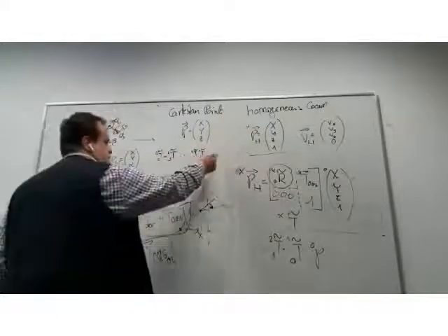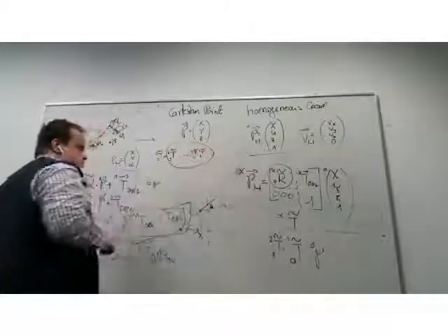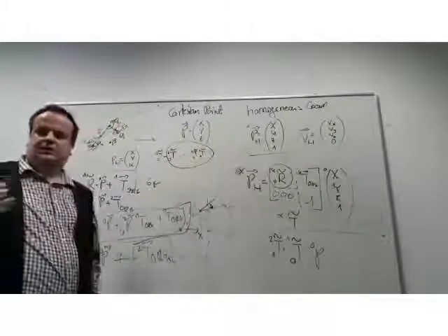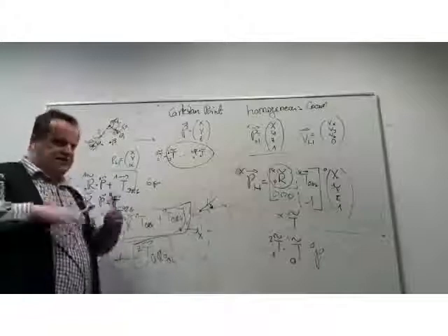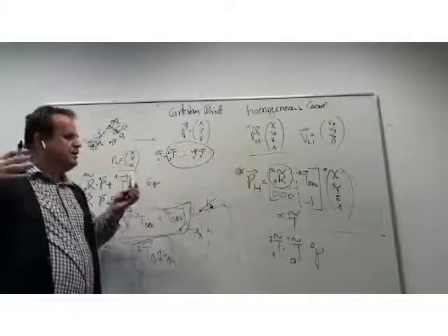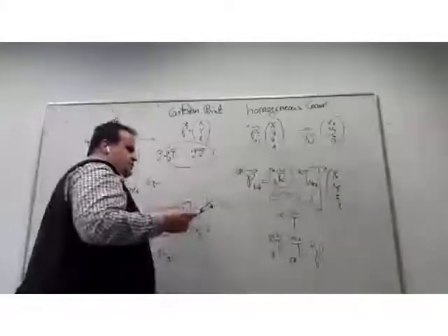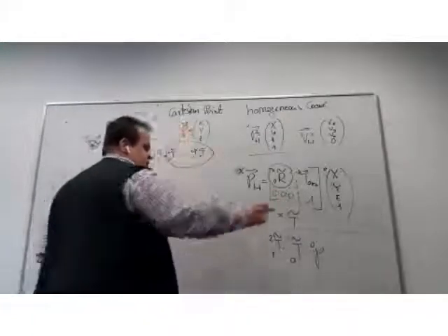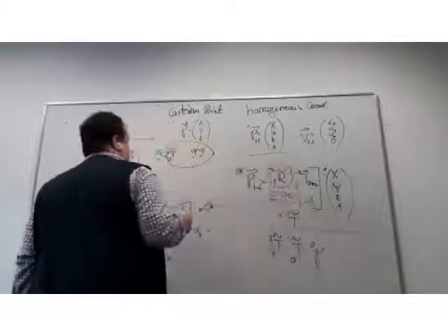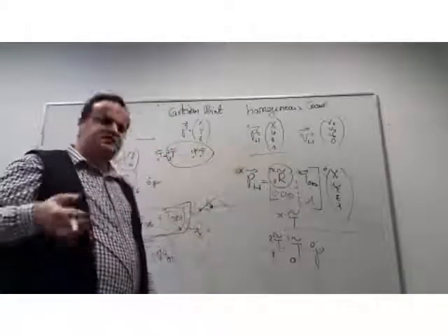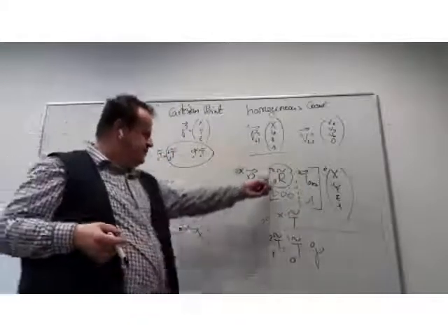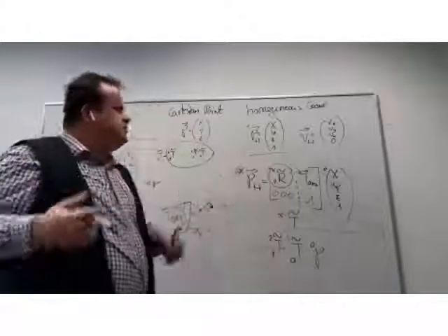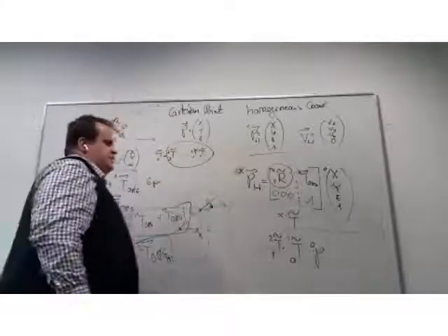Now, if the robot has a static position, I can pre-multiply these transformation matrices into one 4x4 matrix. The 4x4 matrix will also have a structure with zeros in the last line and a one here. And as you will have in the exercise in the tutorial, the resulting rotation matrix will be the product of the rotations.